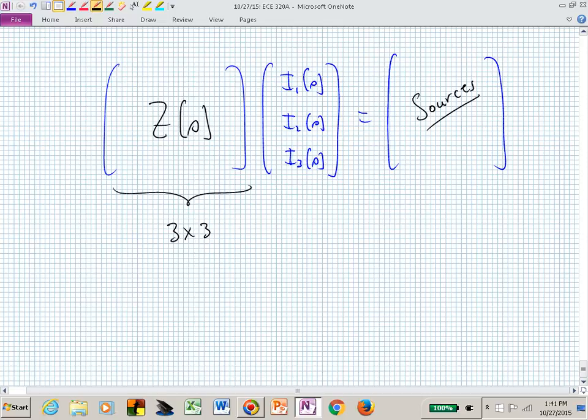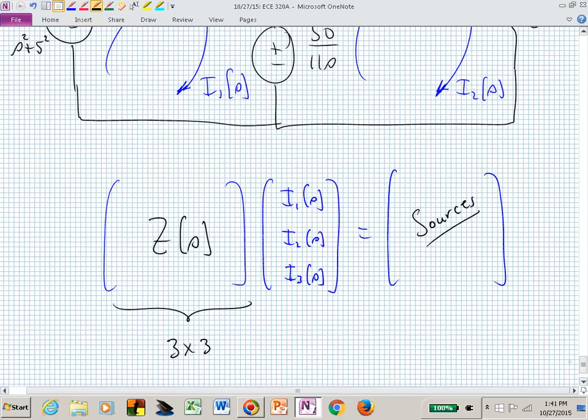Now I noticed on your exams sometimes you would be writing equations and you're just trying to find equations, but sometimes you would be adding voltages and currents. You had V plus I. Is that quite right? So that's a way to check your work. When you start writing an equation, you could just say, what are the units on each of these terms in my equation? Ooh, I've got a voltage, a current. I've got something wrong here. If your equation is voltages, they should all be voltages. If they're currents, they should all be currents, and that's what we're getting here. ZI are voltages, my right-hand side better be voltages.